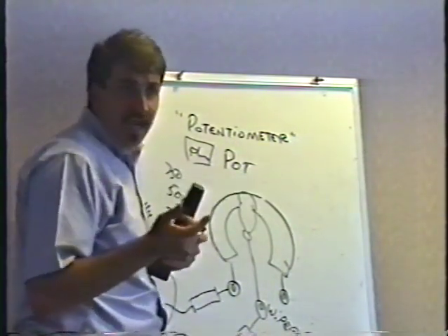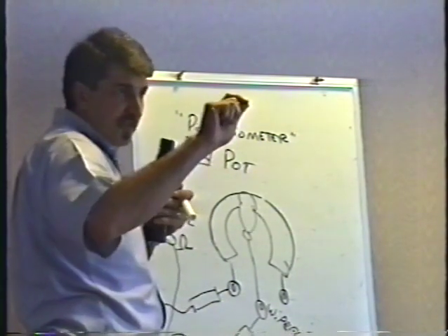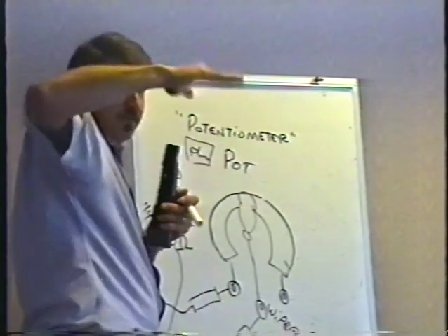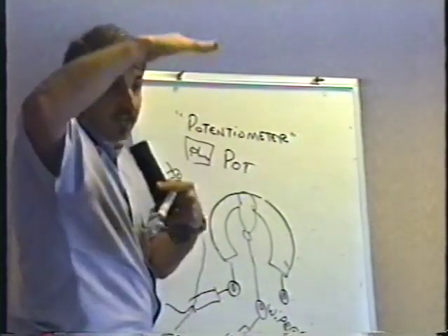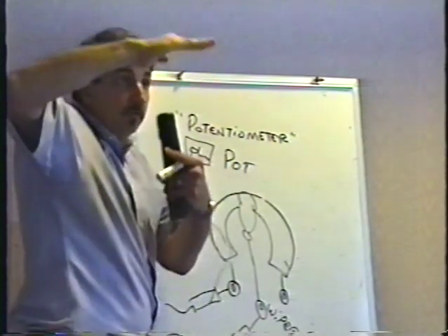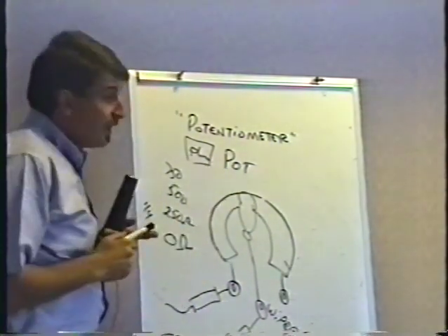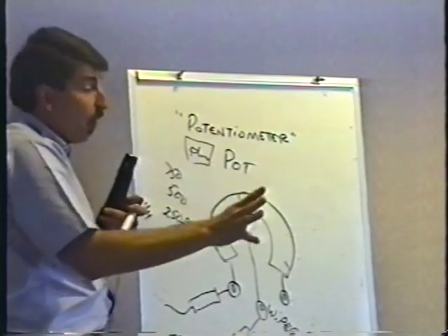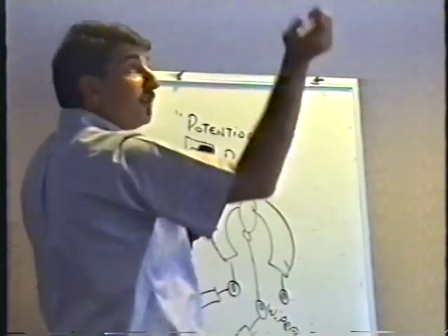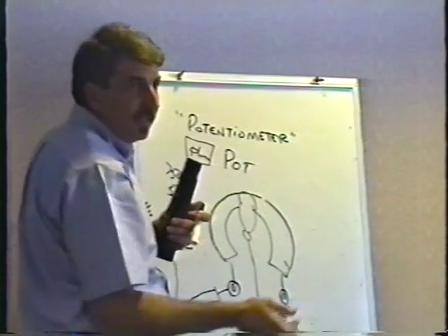And typically in a game, what will happen is you'll go to adjust the power supply voltage, and as you just barely move it, the thing jumps up and down, the voltage fluctuates like crazy. Or you're adjusting the vertical size control of a monitor, and it just jumps all around like this. Usually the pot's just bad, and usually all you have to do is rotate it a few times back and forth, which you don't want to do with the power turned on because you're adjusting something crazy. Turn off the power, adjust it back and forth. Usually that cleans it off.